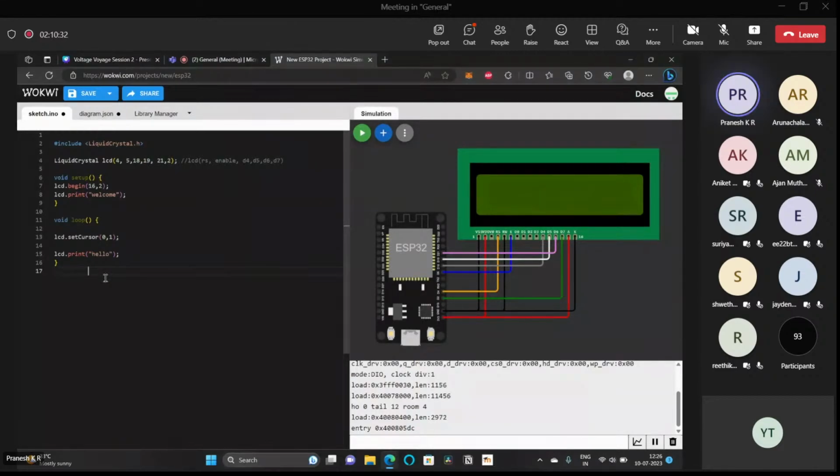I pressed control space and I made it here. Like similarly, inside this LCD display, you can change the cursor point to a point that we desire using this function. So the first input we give is the character in that row in which the cursor should be in, and the second one is which row the cursor should be in,